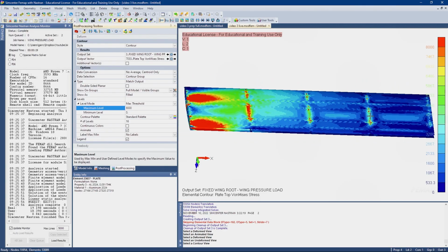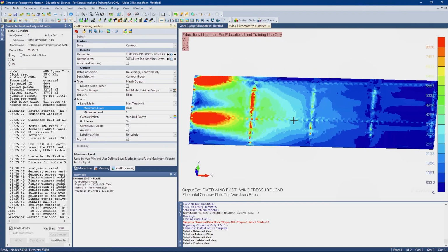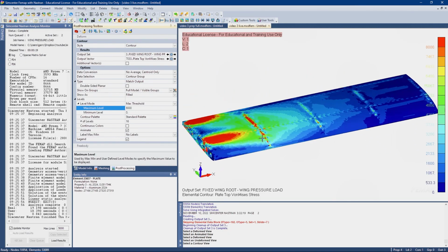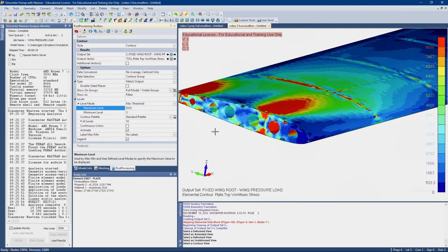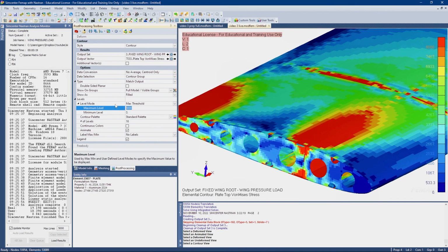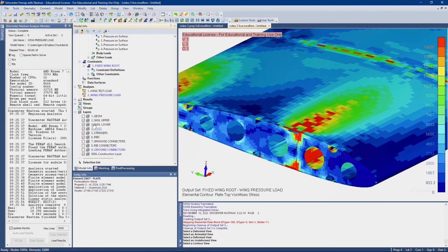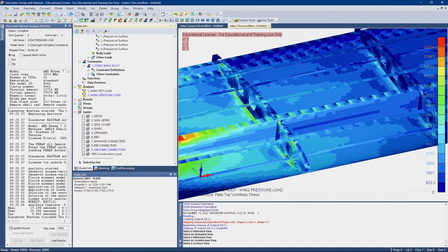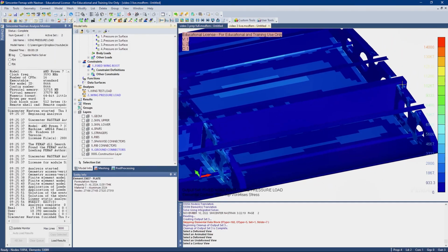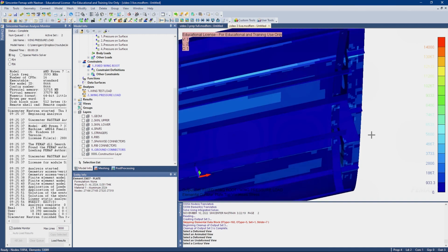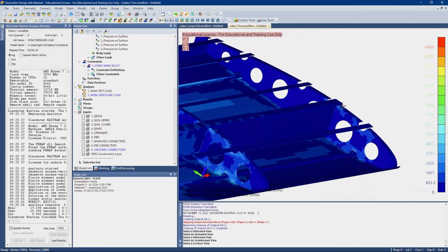And as we get closer to the root of the wing, as you expect for a cantilever beam, the stresses get higher and higher until right at the root, we have some very, very high stresses. Set this to 14,000, and I will turn off our upper skin. So again, you're looking at our spar here. We have very, very little stress. All the way at the tip, we have almost no stress, just a little bit from the connection to the rib.